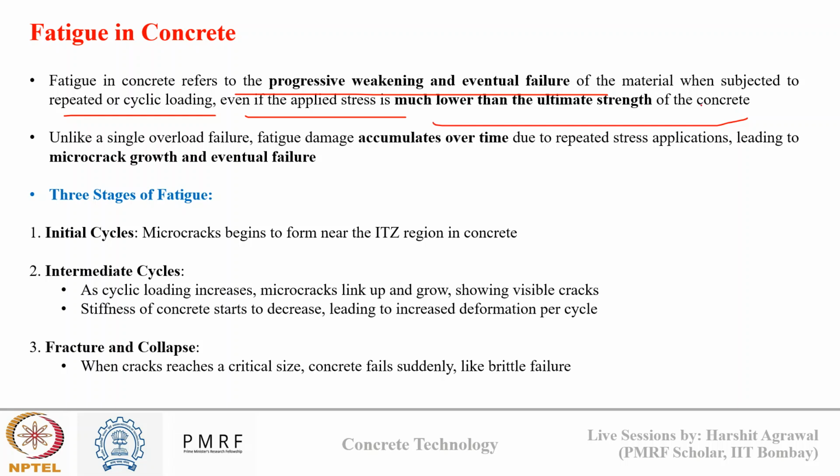Simply saying, say I'm applying a load on concrete of 30% of maximum load Pu, and I'm removing that load after some time, then again applying the load, then again removing the load, and so on in a cyclic manner. This cyclic loading and unloading causes weakening of a concrete structure over time, and this weakening is known as fatigue.